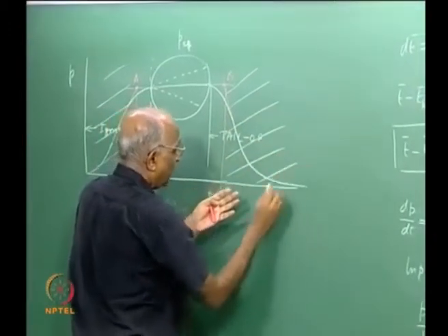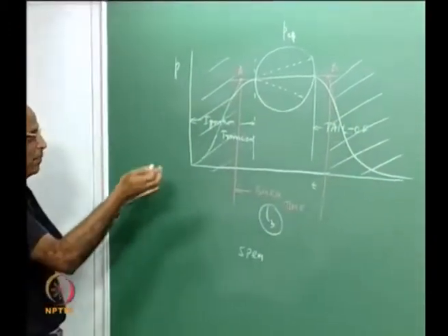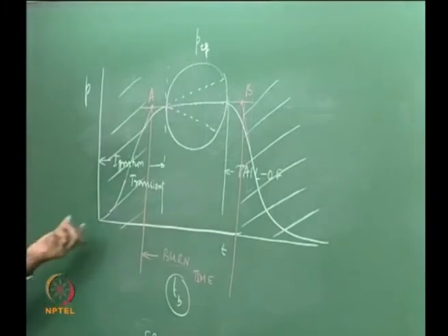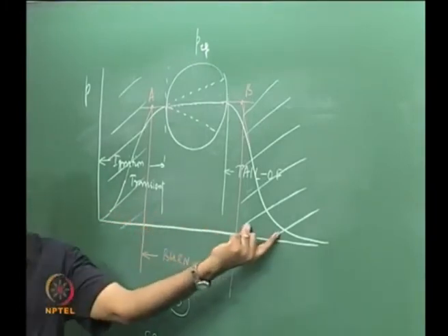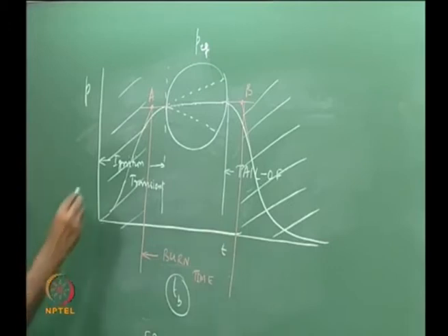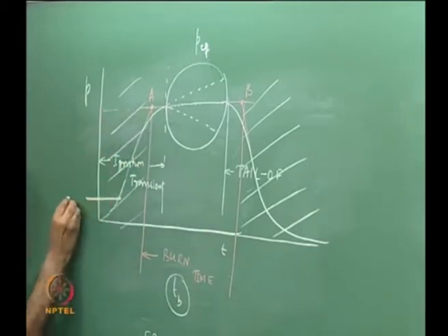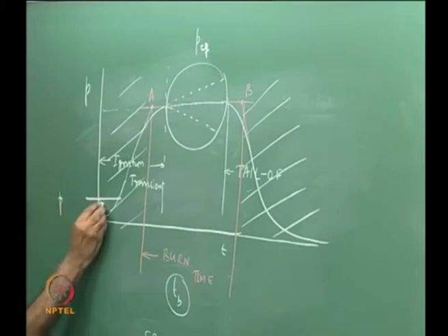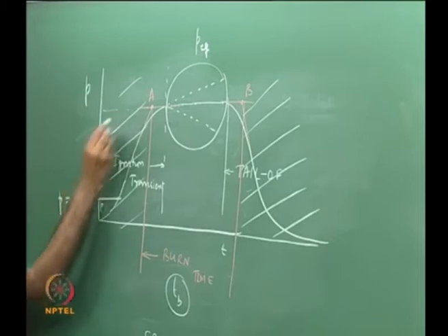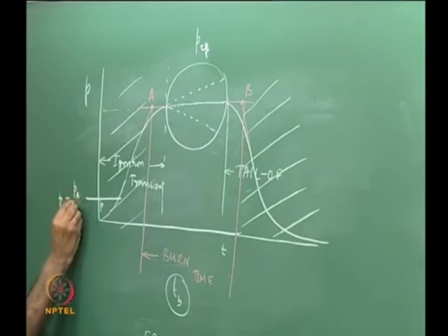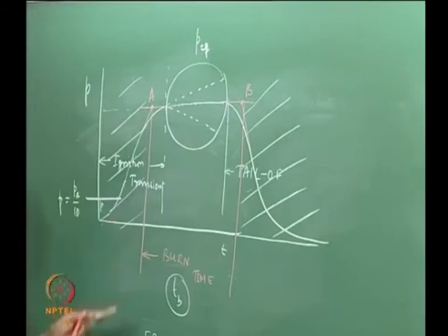Therefore, when I want to define a mission, where the mission is to get impulse with which the payload goes up, this also contributes and this also contributes. In other words, I take the maximum pressure reached over here, and find the point corresponding to A at 1/10, that is 10% of the maximum value.